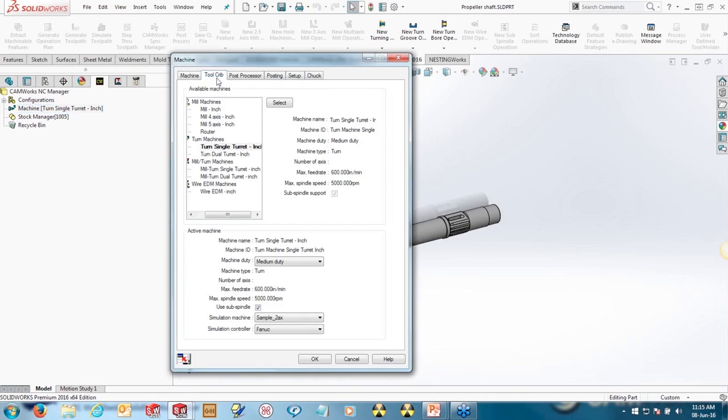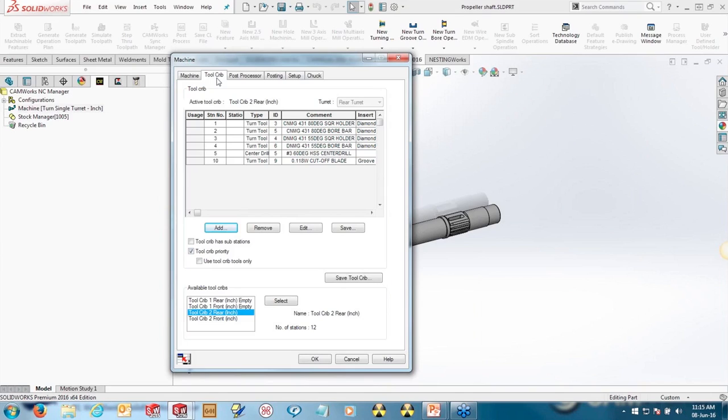As far as your tool cribs go, this is where you can build your tool cribs and match them exactly how you have them in the shop, whether the tools live in that machine, and you maybe change a few of the higher tool numbers out. You can build it up that way, or you can just build, say, one tool crib and have it automatically be used for all the different machines, and you just switch them out whenever you need to.